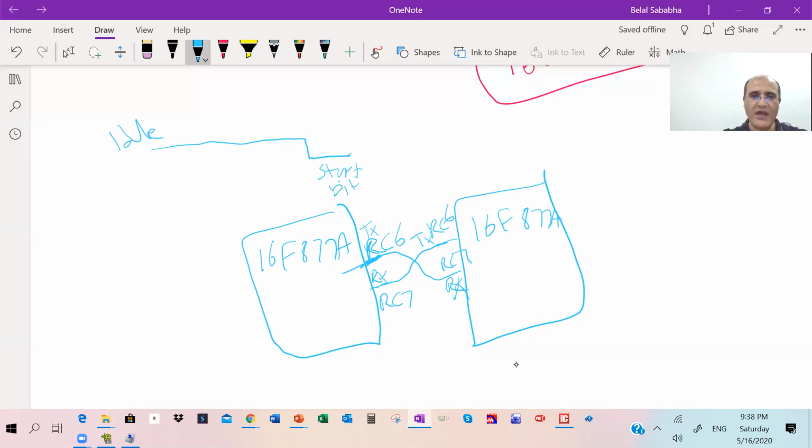Okay? After the start bit, it stays on the line for, say, 1 millisecond. You stay low for 1 millisecond. This falling edge would probably trigger the hardware and make it wake up and start counting. Then you start sending the 8 bits.